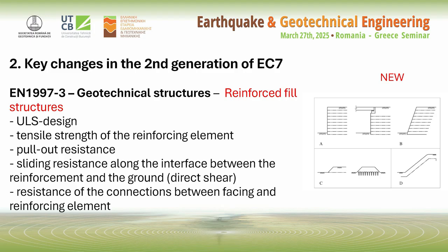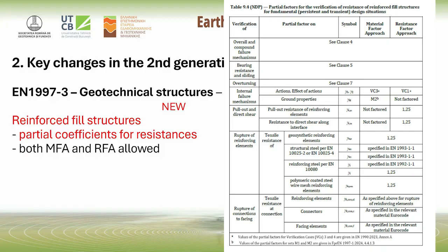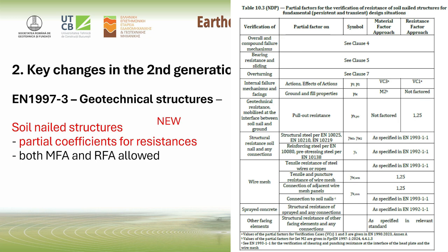In terms of reinforced fill structures, here I will not insist more because it's a completely new chapter and there are many, many things to consider. We will find all the applicable ULS here: the tensile strength, how to determine the tensile strength of the reinforcing element or the geosynthetic, the pull-out resistance, the sliding resistance, and so on. And again, both options are available, MFA and RFA, so each country will choose between those two. The same is applicable for soil nailed structures, again with the two choices.